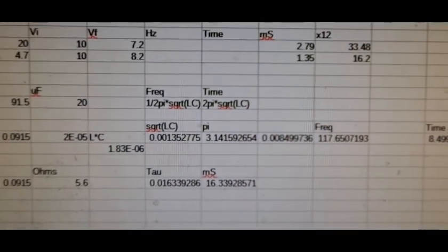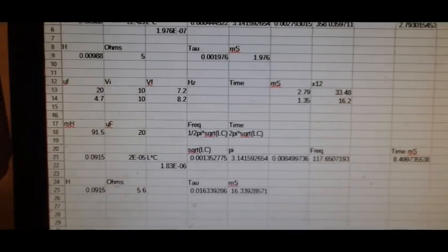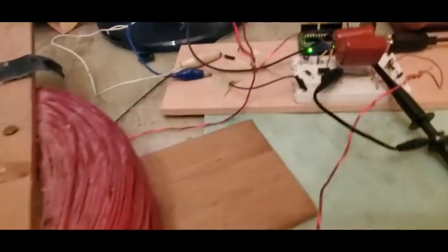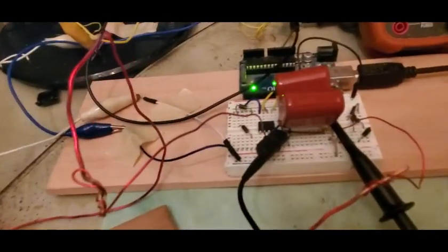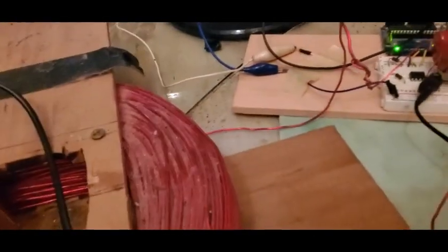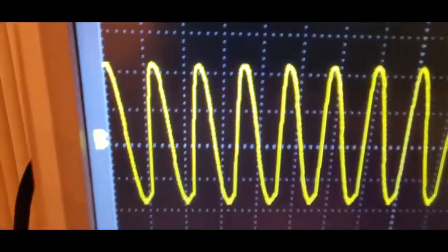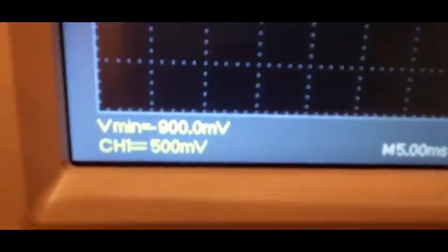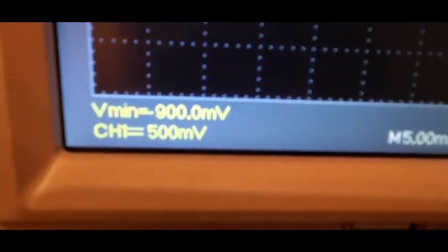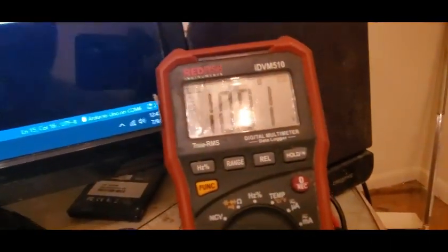So how far negative will this go with 20 UF, and then we'll go to 4.7, we'll go a bit lower. All right, so here we're running this with the 20 UF through here. Now what we see is it's going from 10 down to negative 9 volts. And it's at 10.01, sue me. I mean, it's hard to dial that in exactly right.